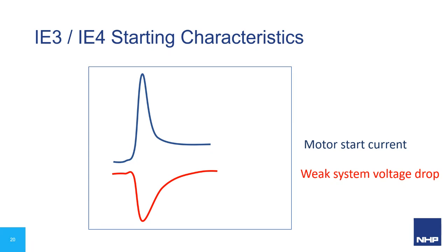Now, the voltage drop may cause that coil voltage to fluctuate, and this can either reduce it or cause the coils to actually start to drop out and the contacts to fluctuate. So the contacts will slightly open and cause impulse cycling of the coil's magnet system. This in turn can cause contact bounce in the contact set. This event alone may drastically shorten the life of the contactor.